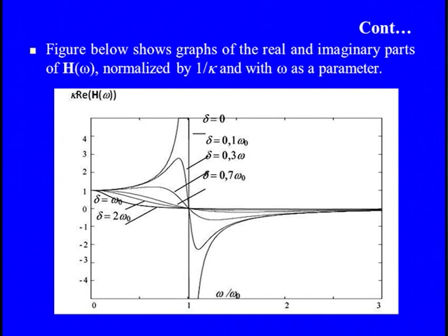You can see the straight line where zeta is 0. But as damping comes into the vibration signature, you can see a straight reduction, or the vibration amplitude is now under control. So, we can straightaway determine the optimum value of damping to damp out the vibration amplitude critically.